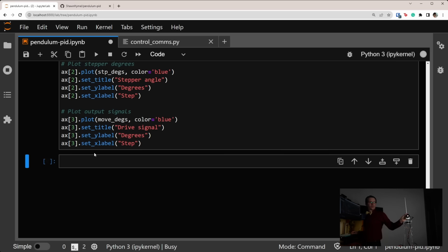Say, for example, move by 3 degrees or -3 degrees in the opposite direction. So if we go to our main interface program here, scroll down to where we see setup, we configure everything, and then in loop, we simply wait for those actions to show up from the PC side. We move the stepper as requested, say by a certain number of degrees. We get the encoder and stepper angles, we put those into an array, and then we send that observation back to the PC, and that is our entire loop and how we're going to control our inverted pendulum.